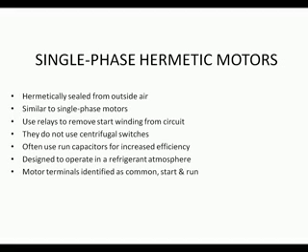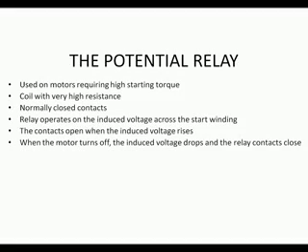A 3-phase power supply is shown here. You have an L1, an L2, and an L3. Those are legs. These power supplies are generated 120 degrees out of phase with each other. If you take a close look at any moment of time, if time is across the bottom, you will see that there's no more than one phase crossing 0 at one time.